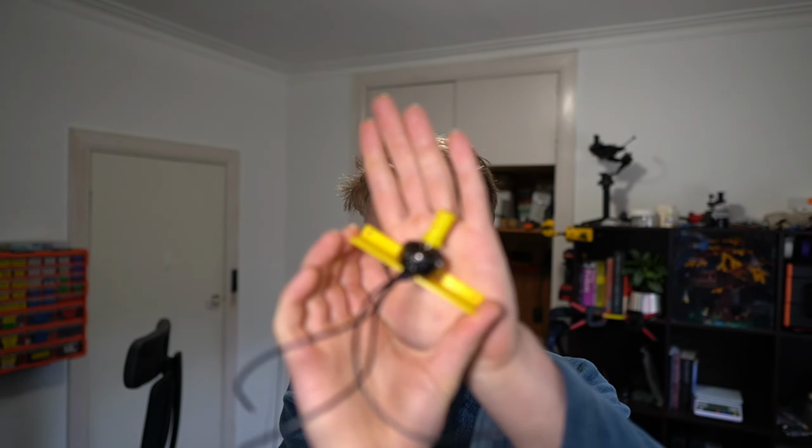But this motor just has way too much inertia. No matter how hard I would throw the ball down, it would still just recoil off of the hand, because it wasn't coming in with enough force or enough momentum to get this moving. But I have changed over to these teensy little tiny drone motors, which have zero inertia, and now it works great. So maybe I'll show you how things are set up on the robot itself.